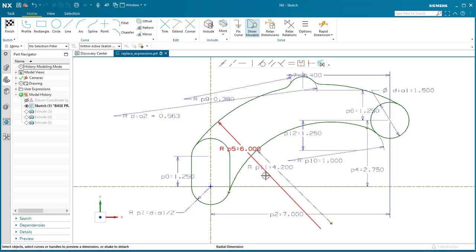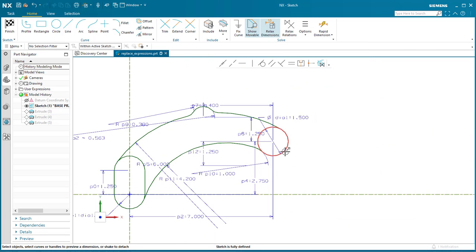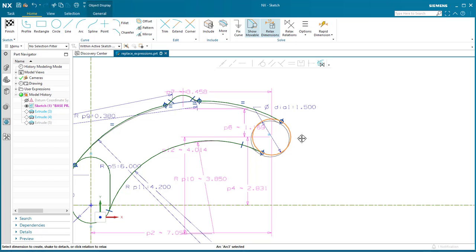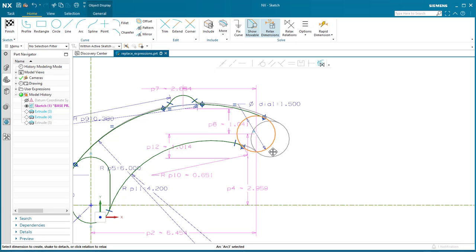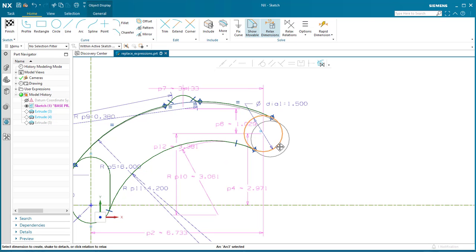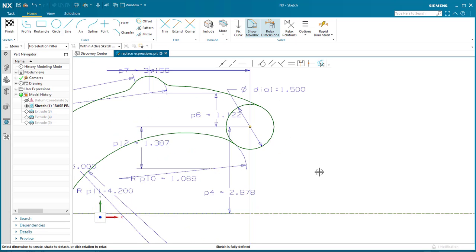So the new sketcher environment includes the solve group, which is the new solver in a way. You're able to see which sketches or lines are movable by a color. I will go into that here in a little bit. You can relax the dimensions. For example, if I enable the relaxed dimensions, I can go ahead and select the circle here and move it around to a different shape. It'll update the dimensions, but it just depends on what you're looking to do.